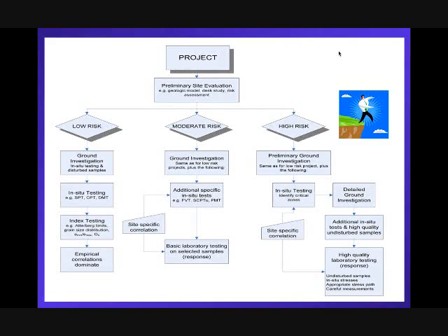So for low-risk projects, often a very simple site investigation involving in-situ tests. In the old days, that would have been the standard penetration test. Nowadays, it involves things like the CPT or the flat dilatometer. And then that's often linked to just small disturbed samples where you can do index testing. And then often those two are combined with simple empirical correlations for basic design.